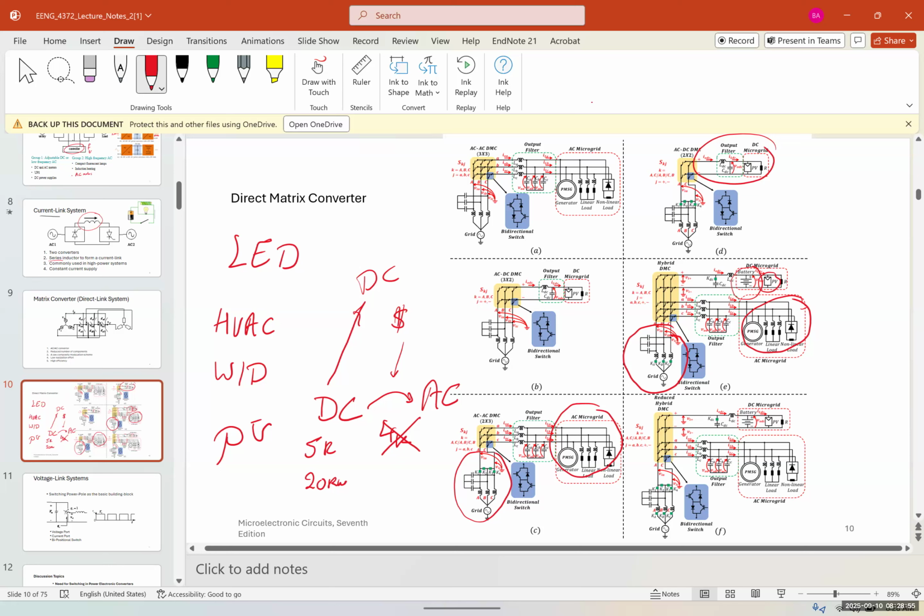And the other benefit of the system is the loss in the system is almost none, because you don't want to convert AC to DC and then back, or DC to AC and back to DC. Because that's what technically these lights and these chargers do, and you have like 40-50% loss in the system. You're going to directly give a 5-volt, like a USB outlet around the house.